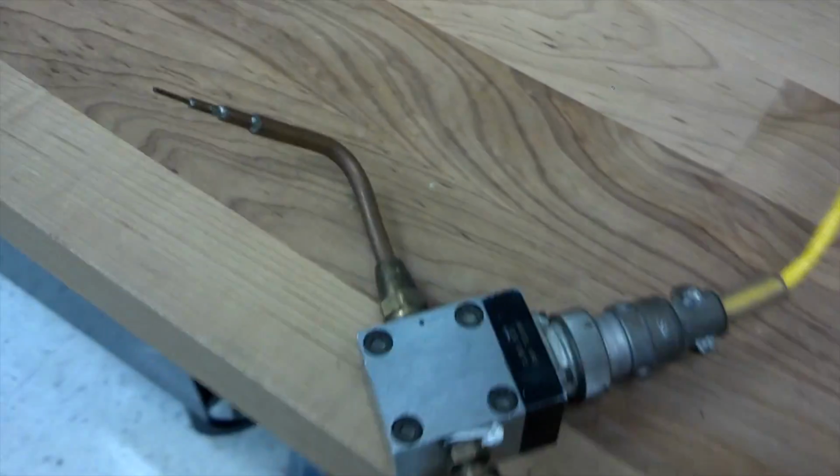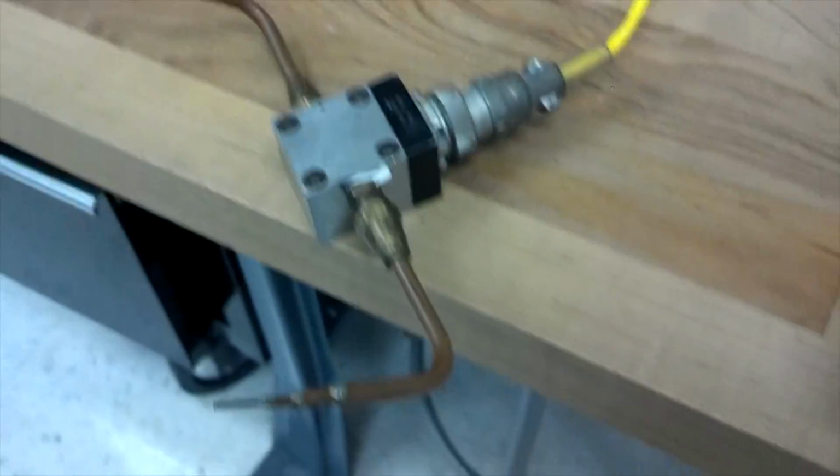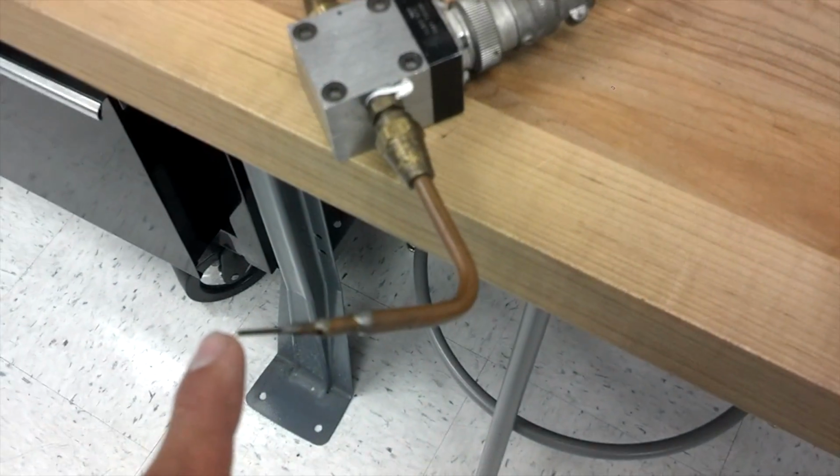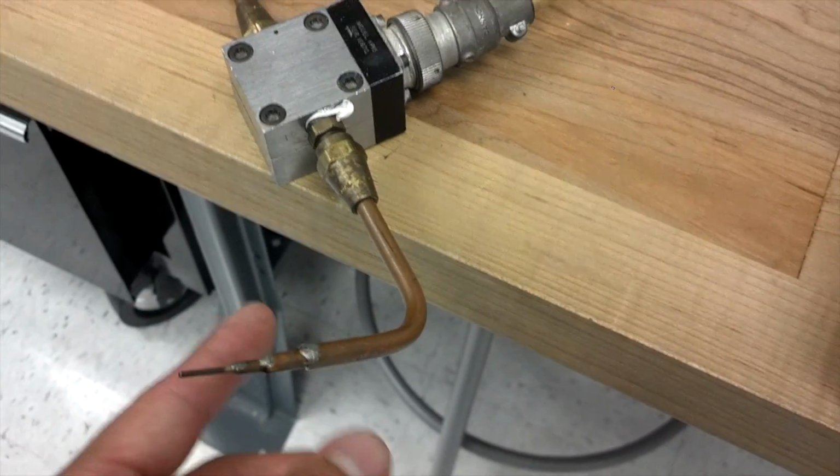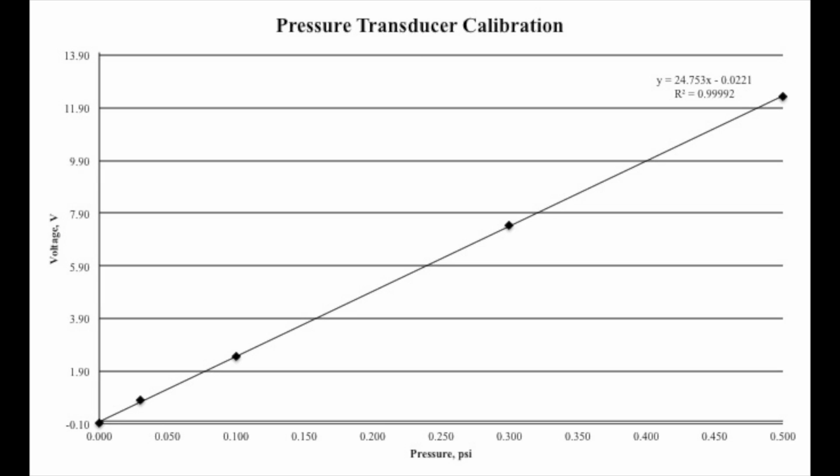This should always remain at 10 prior to any adjustment. Now that the calibration of the demodulator has been performed, the calibration of the pressure transducer can occur. Once the connections are verified, you can proceed to obtain values. The calibration starts by having a known pressure applied to the stagnation port. While the stagnation pressure is applied, the voltage is read from the data acquisition system. This voltage is recorded with respect to the pressure applied.